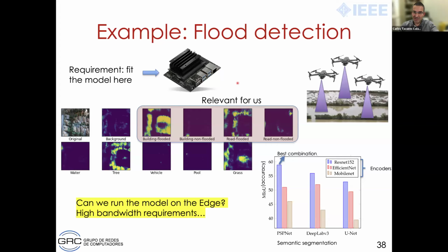So in addition to the problem that the drone must be able to carry these additional devices, which represents extra weight, it's also consuming a significant amount of power. I discussed before that a UAV, because of the LiPo batteries, can fly for 20, 40 minutes. If you are diverting part of that power to one of these boards, and it also has to carry more weight, then instead of 40 minutes, maybe you have only 15 minutes. And 15 minutes may not be enough to accomplish the mission that you had in mind firsthand. So all of these trade-offs must be well studied and accounted for.